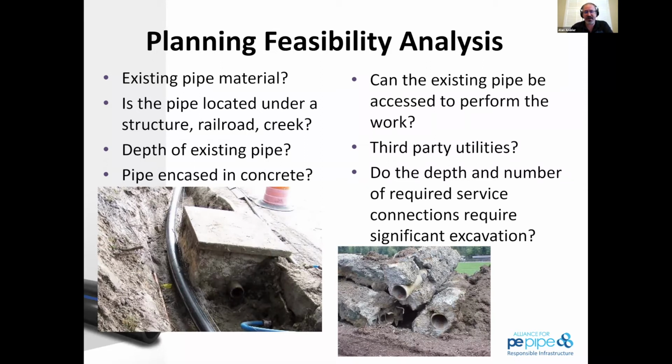The picture on the bottom right does happen to be what has previously been considered a showstopper. All that means is that pipe bursting equipment cannot push out the surrounding soil in the effect that we have concrete encasement. It just becomes another excavation. We already know that we're going to have excavation on this project. This is just another pit.